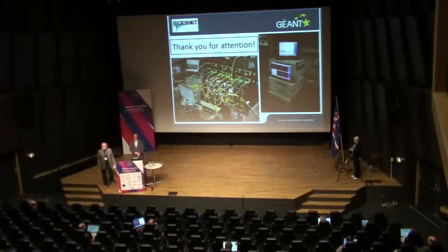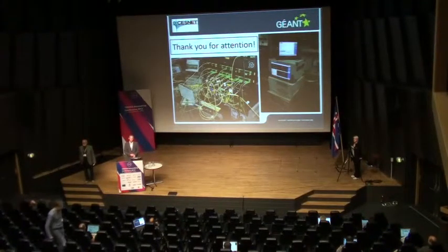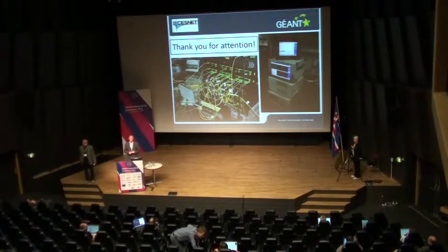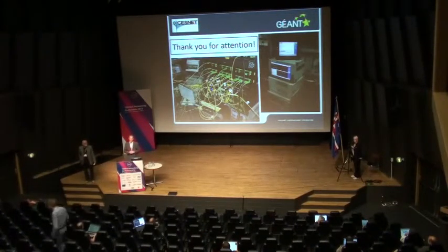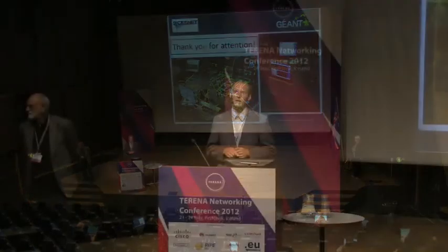Question, okay? You mentioned on one of the slides that the nonlinear threshold is 22 dBm. Well, yes, that was the threshold in our measurement for a 100 kilometers long span. So actually we went a lot below this number, but we found it as a threshold for 100 kilometers of standard telecommunication G.652 fiber.